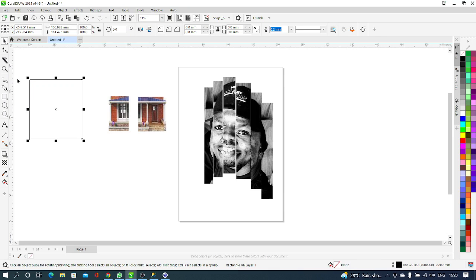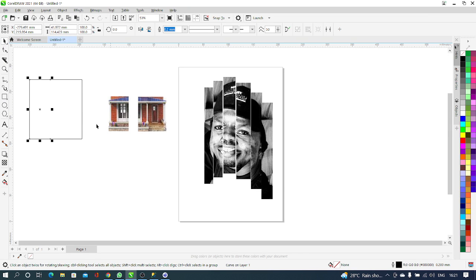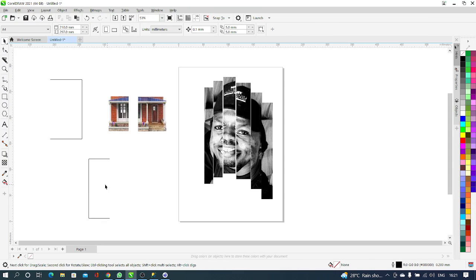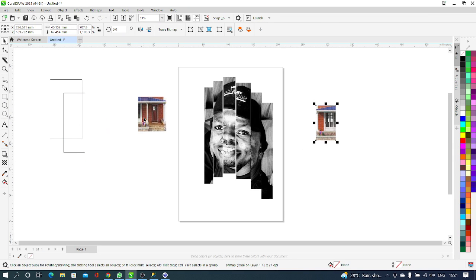Once the image is selected, I can use the knife tool. You point your mouse, you will see the edge written on your cursor. You click, hold and drag until you see intersection written, then you release. Click outside, then click the other part that I just cut. Now I can click down to see what I just did. That is for the knife tool.